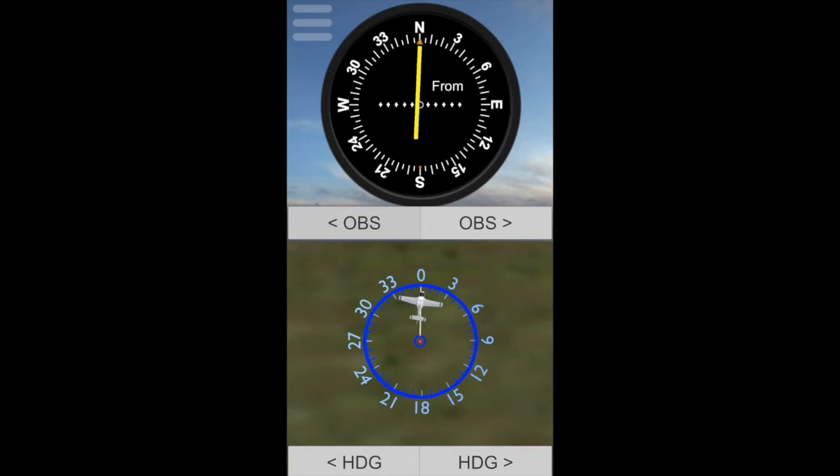Okay, now let's try to move the aircraft around to show the concept of from indicator and a to indicator. We said if I'm selecting the 000 radial, which is north, as you can see on the top half of this illustration, that means if the aircraft is anywhere between the 090 and the 270 on the top half of the circle, I would still get a from indication. On the opposite side, or the bottom half, between 090 and 270, I would get a to indication.